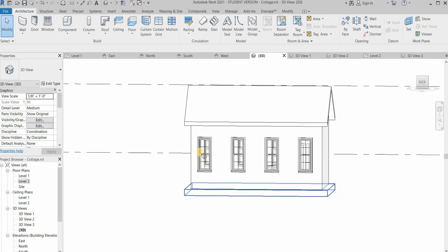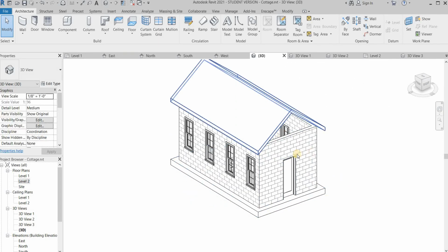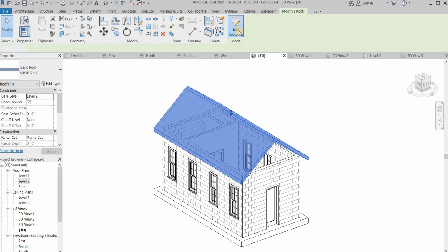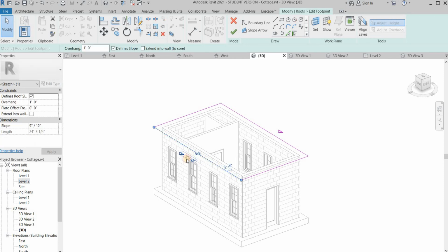I think that looks fine for the slope, but just so that we know, let's change the slope as well. We can edit this in the 3D space as well, so I'm going to do that. I can change this by clicking on it and change it to 5 and 12. Let's do the same thing on this side, otherwise it's going to look weird. So there we go.